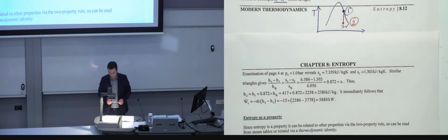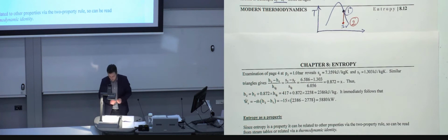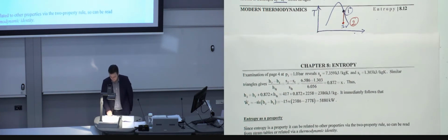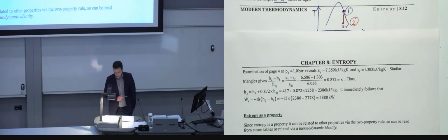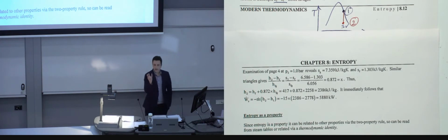We now look for the value of entropy for the second pressure. So the second pressure now is 1 bar. Looking at the steam tables, you find the values of SF and SG. You would need to find SG and SF because these would give you the two limits.